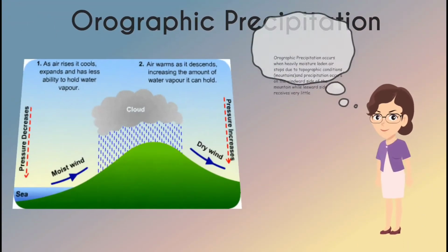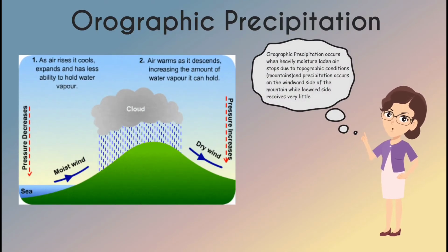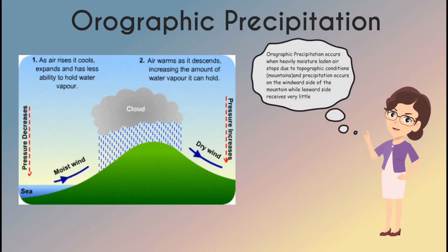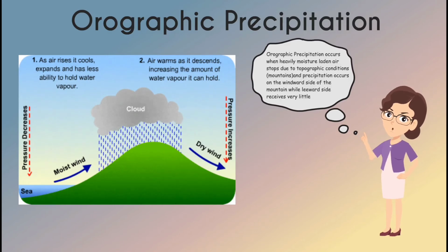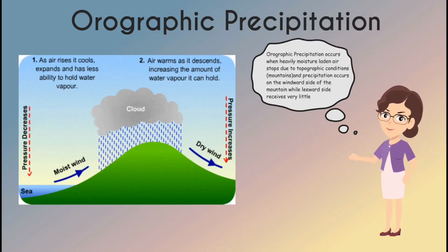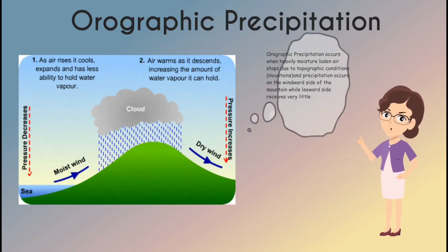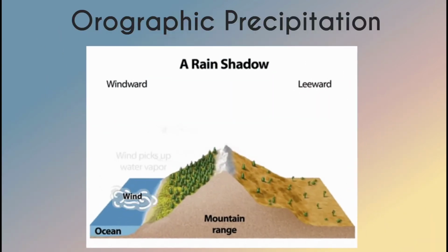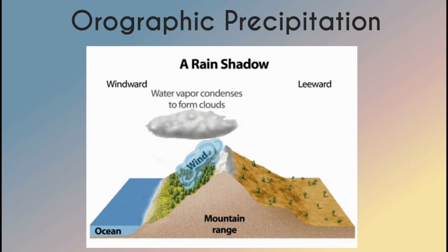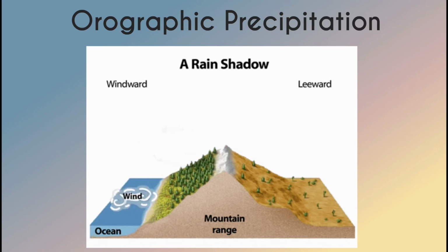The third method of lifting an air mass occurs when air flows up and over a topographic feature such as a mountain barrier. Orographic barriers often supply the lift to set off precipitation. For this reason, precipitation is heavier on windward slopes with rain shadows on leeward slopes. Orographic precipitation that is not associated with cyclonic or convective action tends to be of low intensity with relatively long duration.